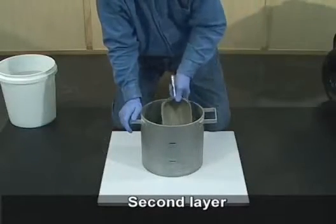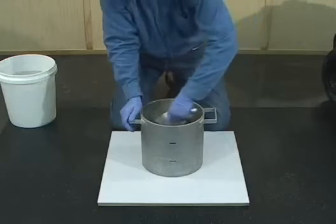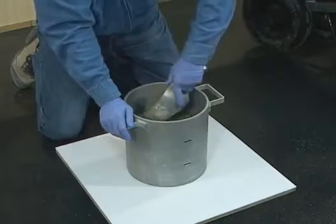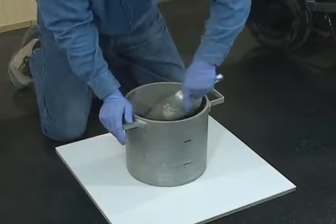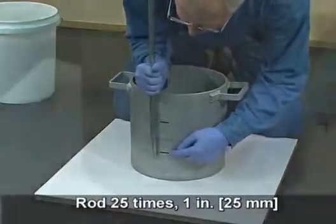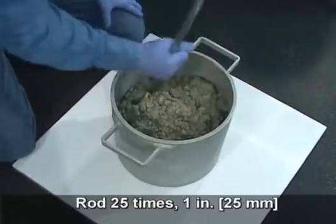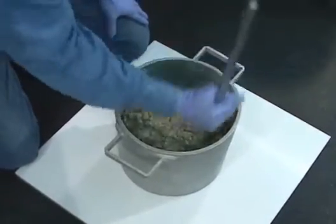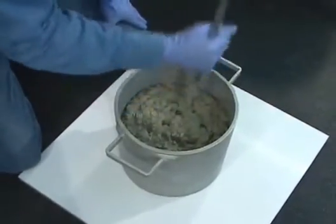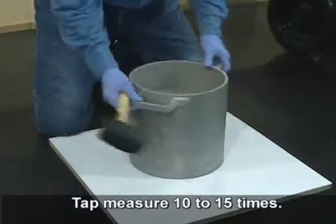Add the second layer of concrete to the measure. Rod the layer 25 times. The rod should penetrate through the second layer and into the first layer about 1 inch. Tap the exterior of the measure 10 to 15 times with the mallet.